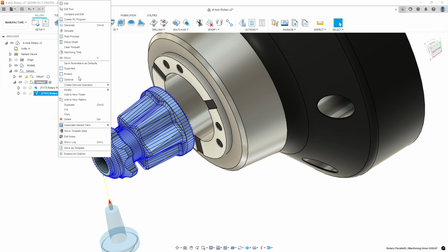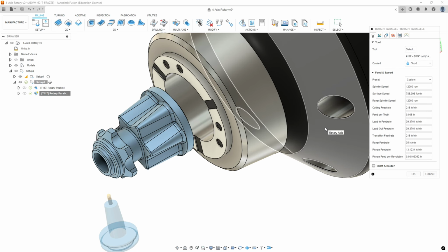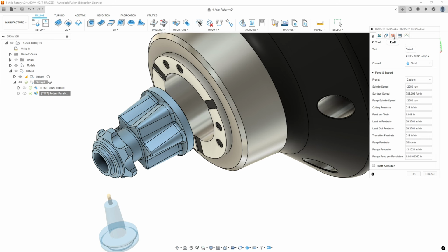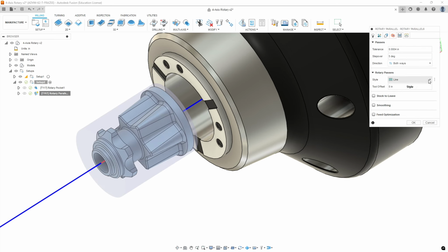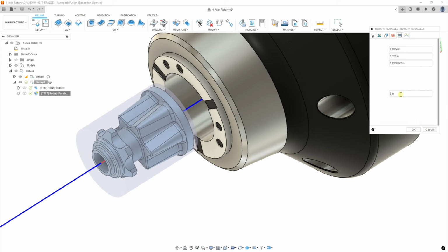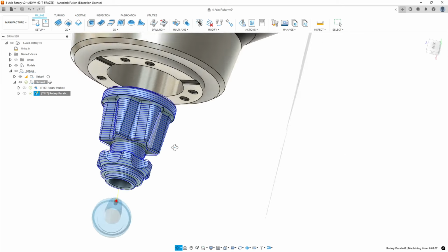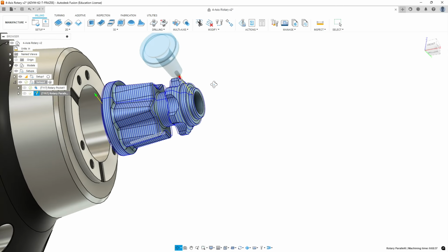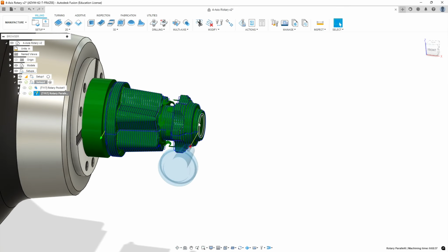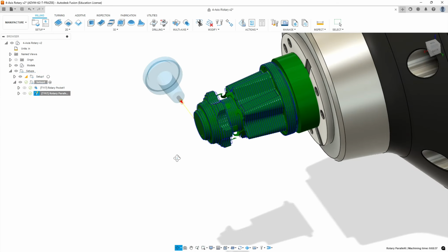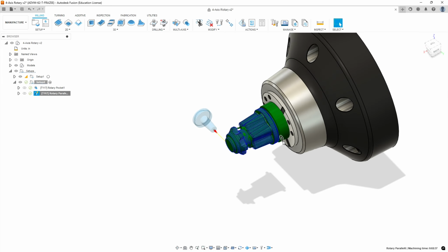Okay, so now let's go back in and look at our third option of tool directions. Instead of line, let's see what circular does instead of spiral. I suspect it's going to be very similar. And so it just goes around, but then it's going to have a sideways move somewhere in between. So if we rotate around, you see that there's this line running the length of the part. That'll leave a witness mark there. So that's where it's moving from circle to circle.